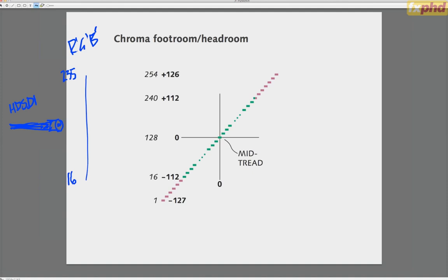But more typically in studio video, we're using a 10-bit scale, so these are the 64 and 940 numbers. But those are what I call interface numbers. And in terms of doing arithmetic on those numbers, you'd really like black to be 0. So I prefer the 8-bit scale 0 to 219, or the 10-bit scale 0 to 876. So that would be R prime, G prime, B prime. That would also be Luma.